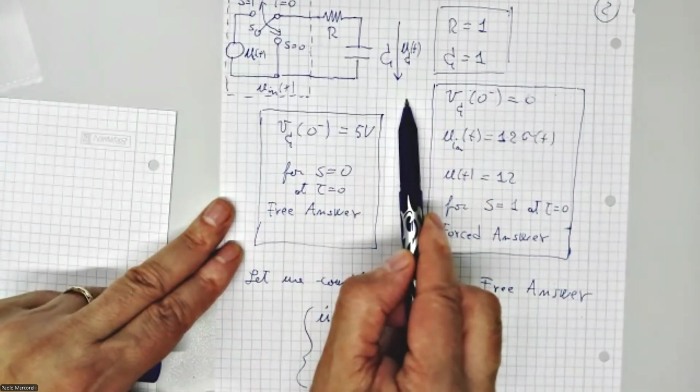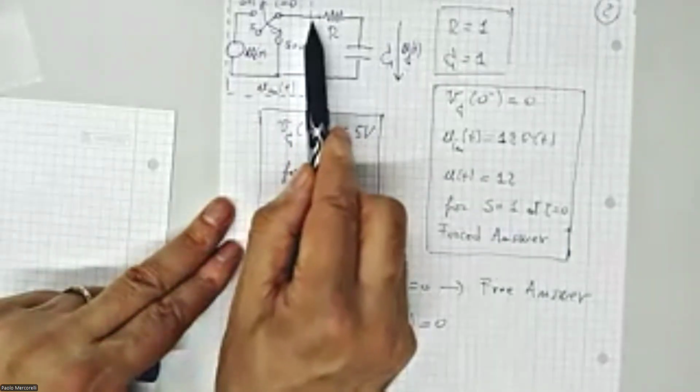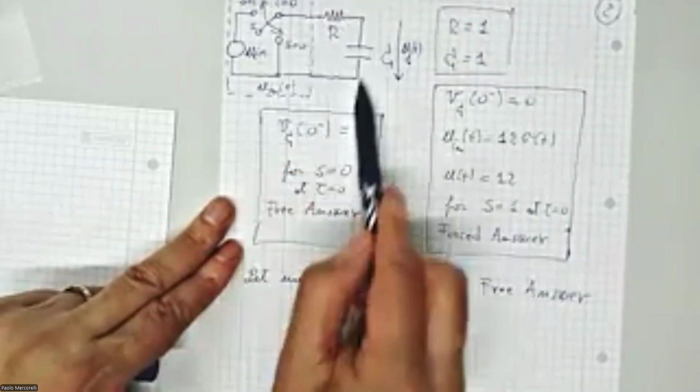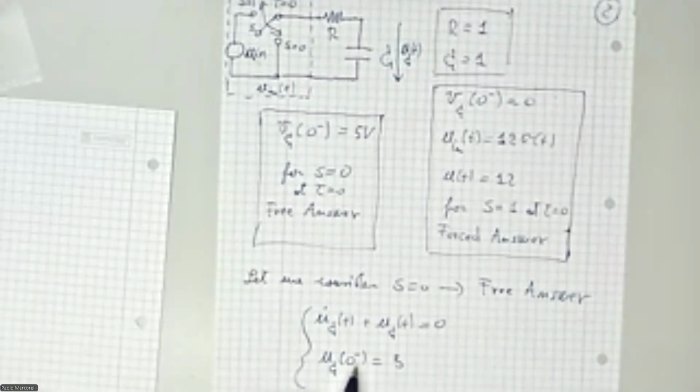You know better than me from electrotechnique. This means UC plus this voltage from here to here is R multiplied by the current. But what is the current in this context? It is C times the derivative of UC. But C is 1, this is the balance. Okay, the new thing with respect to before is this minus.